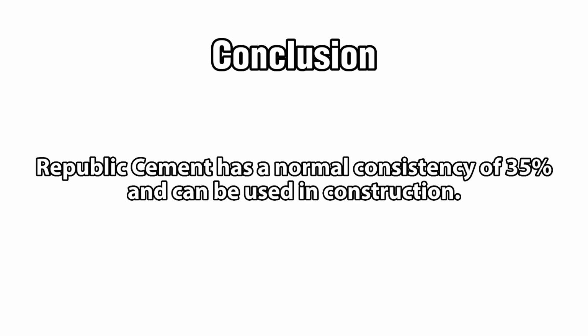In conclusion, the normal consistency of the Republic cement that we purchased, not knowing the conditions it has undergone, is 35%.